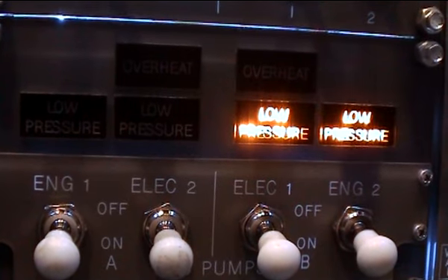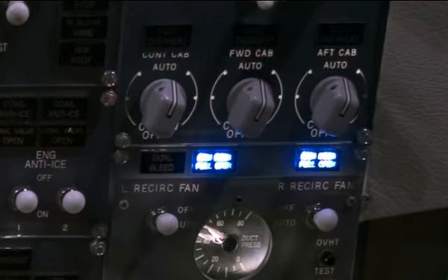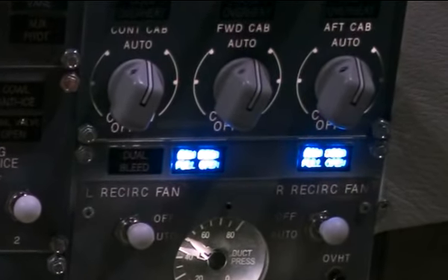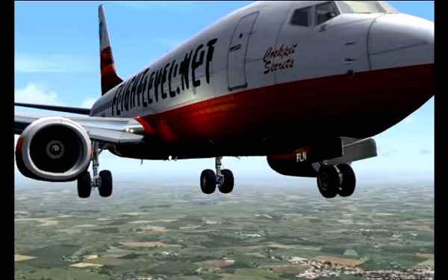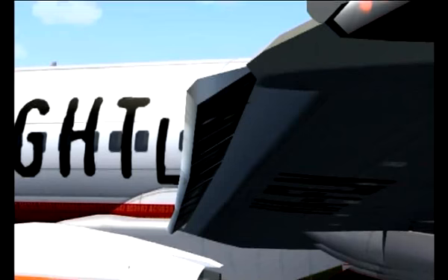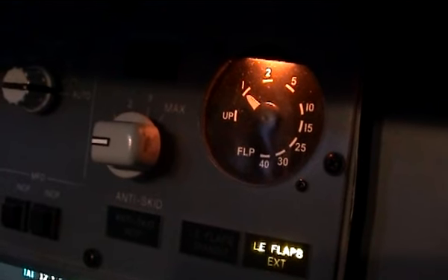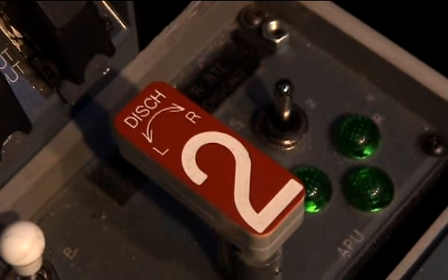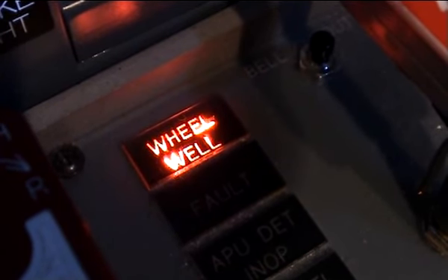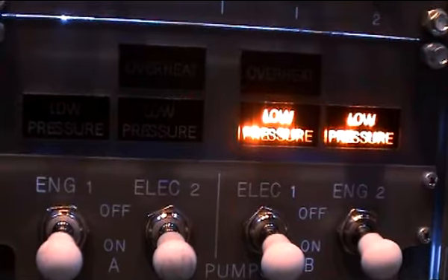The lights in the cockpit have different colors. Blue indicates the operation of electrical systems and valves. Green lights refer to configuration, such as when landing gear and slats are deployed and locked in their correct positions. Red lights call for immediate action, such as in case of fire. Failures that do not require prompt action are indicated by amber warning lights.